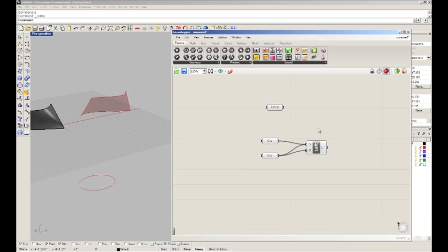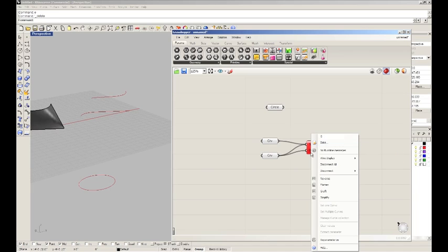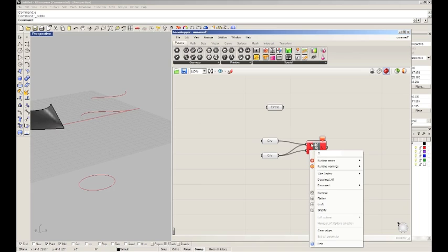Lastly, red in Grasshopper means you've got a problem. Red means that there's a warning of sorts. So if I right-click on this center, or if I right-click on the different inputs and outputs of this, eventually I'll find one that has a runtime error or this red X in it, and it'll be the thing that's telling me what's causing the error.